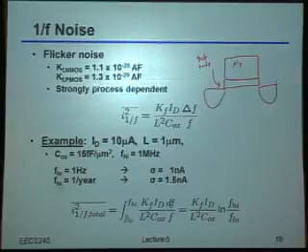Okay? Well, turns out that no oxide you build is ever exactly perfect. Usually there's some kind of quote-unquote defect inside of it that people usually refer to as a trap. Okay? And anytime you've got one of these traps, it turns out that every once in a while, an electron, or a hole for that matter, but typically electrons, can jump out of the poly gate and into that little trap and get stuck there.